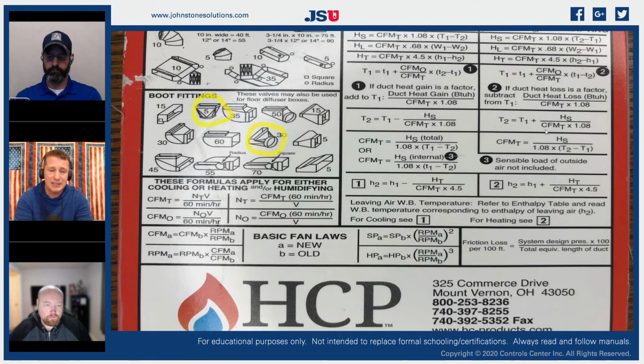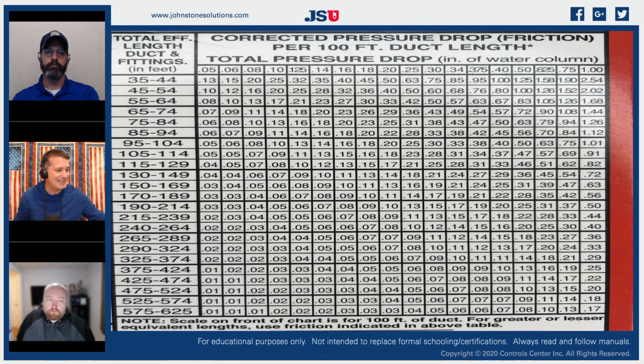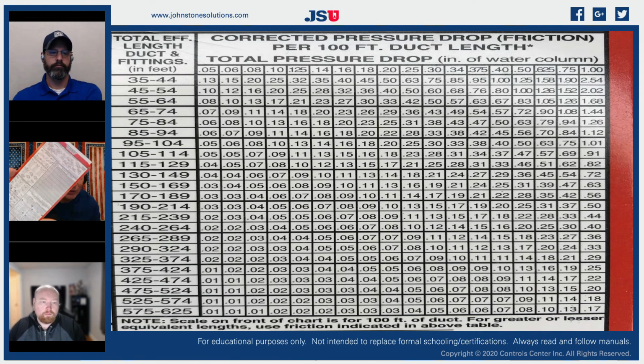And if we took the time to look at those, we would find that there's a lot of restriction in our elbows and in our boots that are not accounted for. If we properly account for these, if we truly want to get an exact representation of what our ductwork is, we have to go to the back side of our chart. We have to go to the back side of our duct calculator and use the chart that is almost never used.